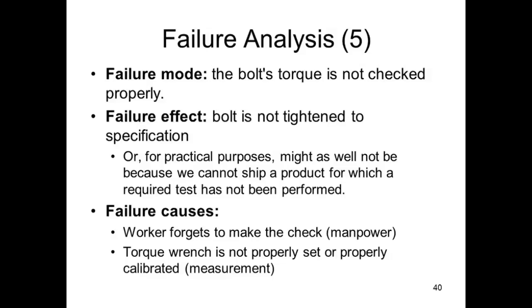So basically, if the worker isn't checking the torque, or if the torque wrench is out of calibration, we're shipping car seats and we don't know what torque the bolt has been tightened to, so we could have a real problem on our hands.